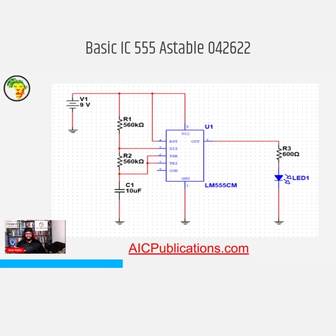What happens is, with the time constant created by the combination of the resistors and the capacitor, the capacitor is going to charge up to a portion of the battery voltage, and then it's going to discharge according to the time constant, and that discharge is what's going to turn on the light emitting diode. So let me take you through the actual circuit itself so that you can see what we've done in the lab.